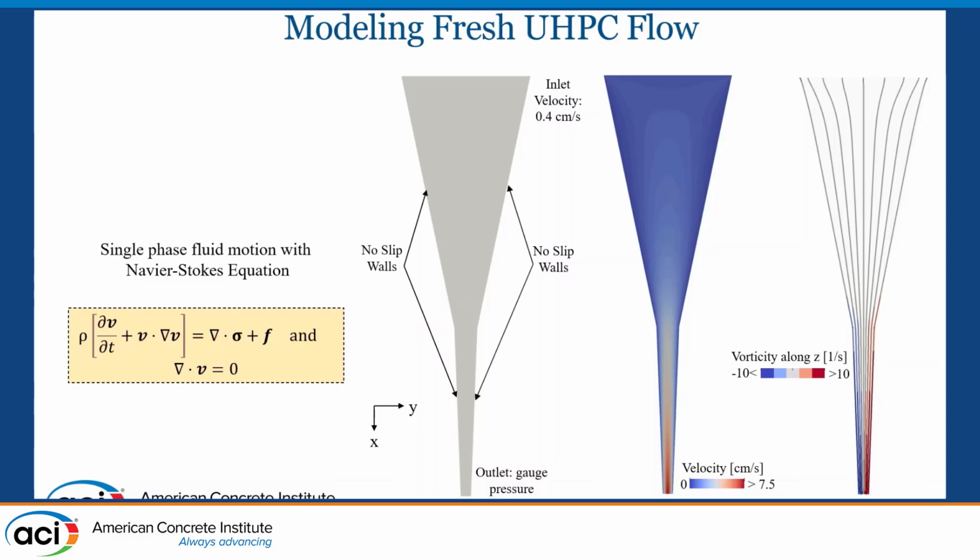Then I went to CFD-DEM, where you use the background fluid using CFD and you introduce fibers with DEM, the discrete element model. But when you put in a fiber amount like 2%, 3%, it's a very difficult job to perform, even with supercomputers sometimes. So we had to neglect that part. We came up with some other models motivated by short fiber reinforced composites, how they predict the fiber orientation in extrusion models. So I used that for my study.